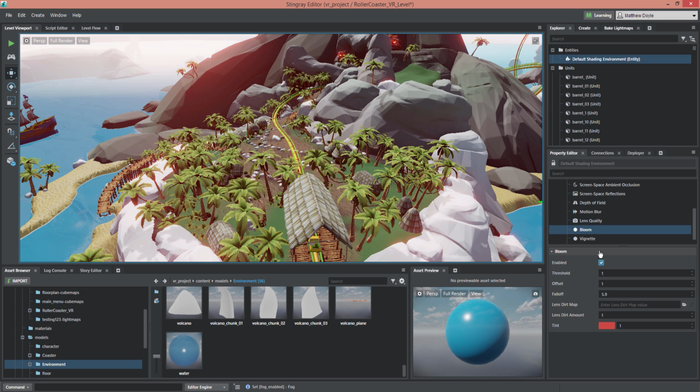Now, these are the only two that I am using. This is what I found I got the best performance for my demo with. And what you're going to need to do is go through these and basically turn them on one at a time and see what kind of performance hit you take in VR, in your Oculus. And if it still runs great and you don't have any ghosting problems or stuttering, then by all means, if you want to use these screen space effects, feel free to use them. Otherwise, you're really just going to have to be careful because, if I were to turn all these on, it gets really expensive and it's going to have a huge impact on the frame rate. And just keep in mind, you've got to maintain that VSync in VR.